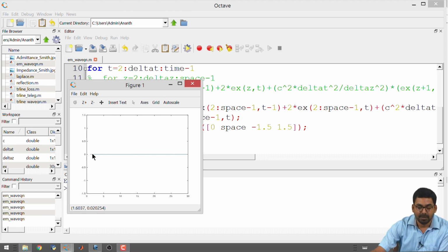It is very important for the wave to travel only once in the majority of the simulations. It is simply because what you are trying to figure out at the end of the simulations is, you can assume that there is a medium or a region in between, and you are trying to find out the parameters of the region in between. You can assume this to be some kind of an open loop control system, where you have an incoming signal and you have a box which has a transfer function, and then it has an output on the other side. You want the input to pass through to the output and not come back, so that you can determine the transfer function h by taking output divided by input. So, you want to make sure that it happens only once.